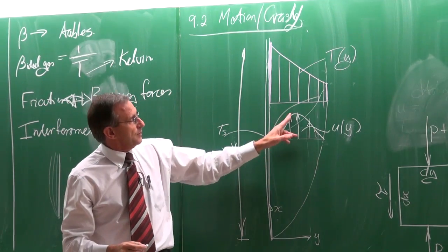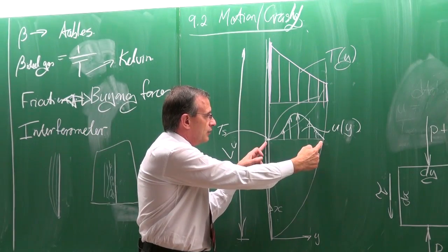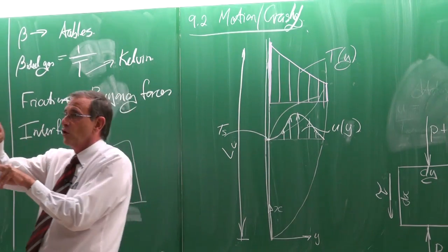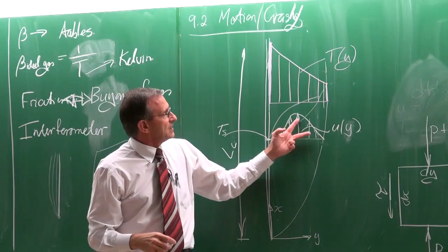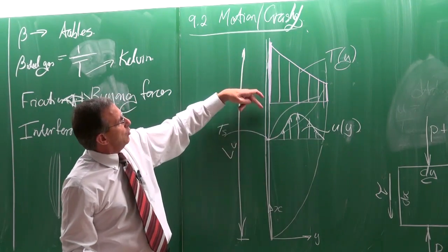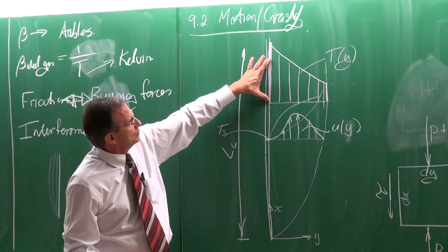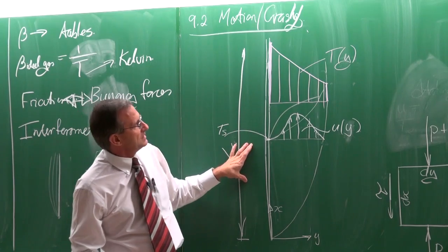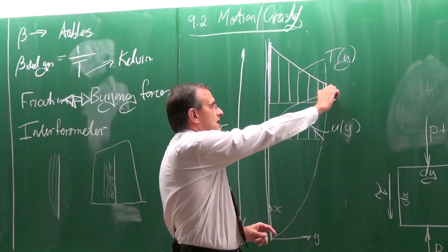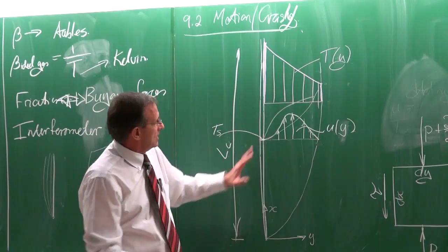So in this case, we've got a boundary hydrodynamically, in which we've got a hydrodynamic boundary layer, and somewhere in it we've got a maximum for the velocity. Okay, so it increases to a maximum and then it goes to 0. Here is the temperature on the wall. The air, if it is air flowing around it, that temperature would be equal to Ts, that of the plate, and then it would decrease to that of the ambient temperature. Remember, this is not 0, except if it's 0 Kelvin. Okay. So this is typically how it looks.